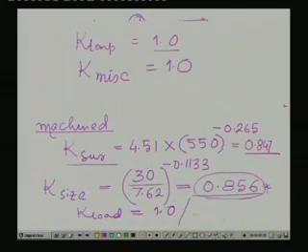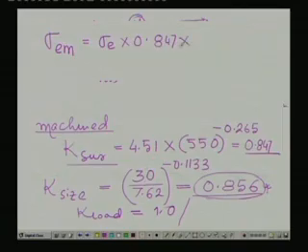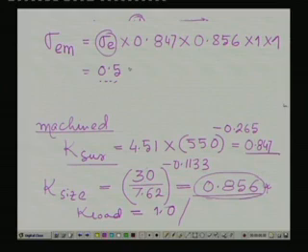So, ultimately what we get is that the endurance limit for the machine member comes out to be the endurance limit for the material multiplied by 0.847, multiplied by 0.856, multiplied by 1, multiplied by 1, and this value we have chosen to be 0.5 into 500, I am sorry, I think it was 550.